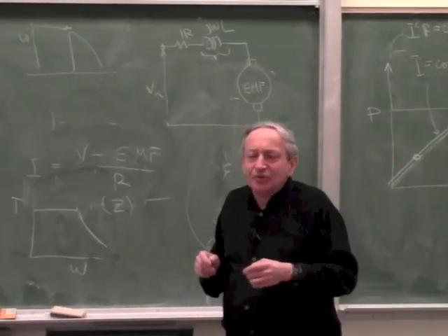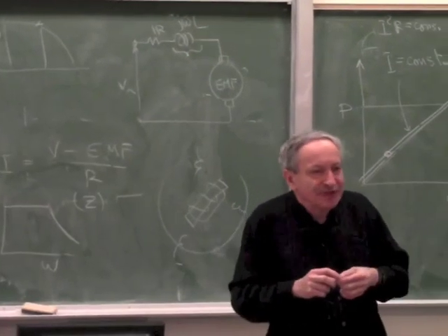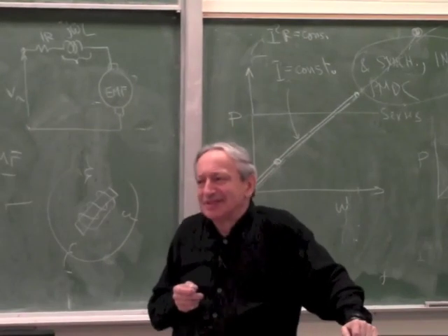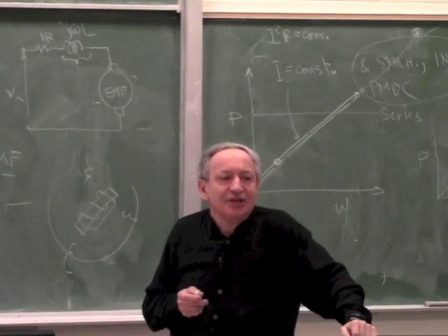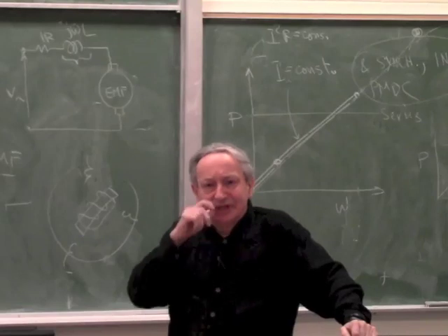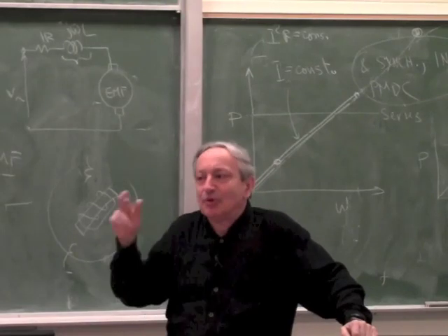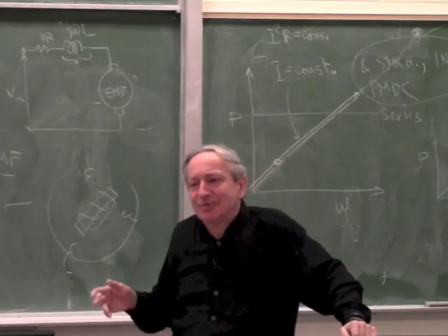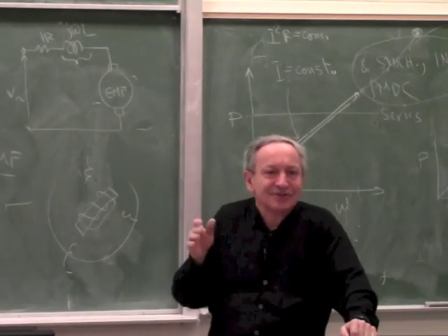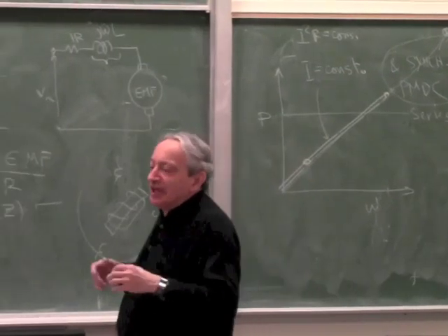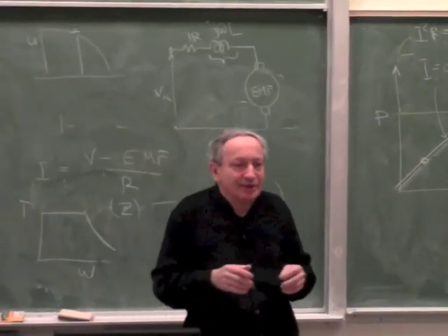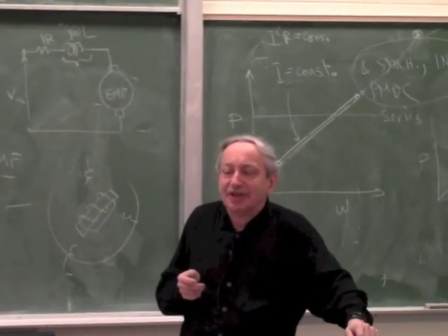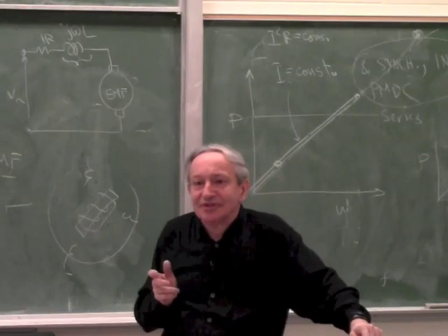So you do gain power, because typically if you really want to make a motor run at a low voltage and efficiently, you have to make it with many poles, because otherwise you end up with a very low frequency. If you make it with many poles, it has many windings, and it becomes bulkier. So if you really want a very high performance motor in terms of horsepower, you are better off making it small and very high RPM. The only side effect is noise.